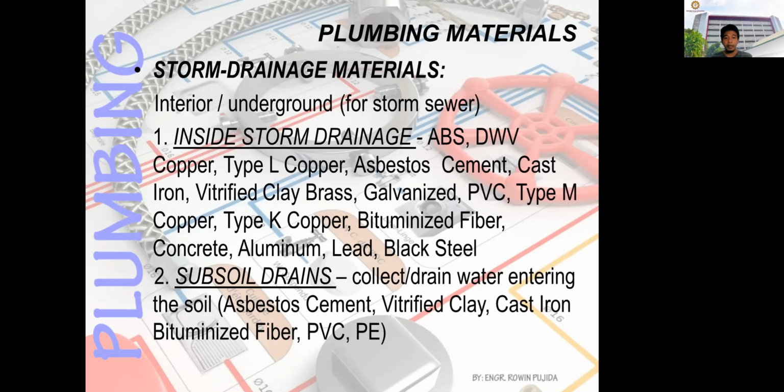etc. Okay. Next, you have subsoil drain. It collects or drains water entering the soil. You can use asbestos cement, vitrified clay, cast iron, bituminized fiber, PVC or PE. So normally in the gutter, we will use the PVC. Ano, not gutter, the downspout.